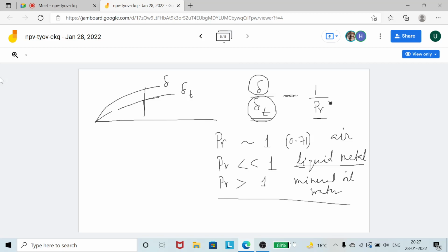So this is something you have to know. So you can see that if you change the PR, there will be more heat transfer. So you go for car, you go for water cooling, that means you are changing PR. So that means how heat transfer coefficient change? If you go from natural to forced, heat transfer will change. If you change the fluid from gas to liquid, it will change. And you get maximum heat transfer when you do what is called phase change.